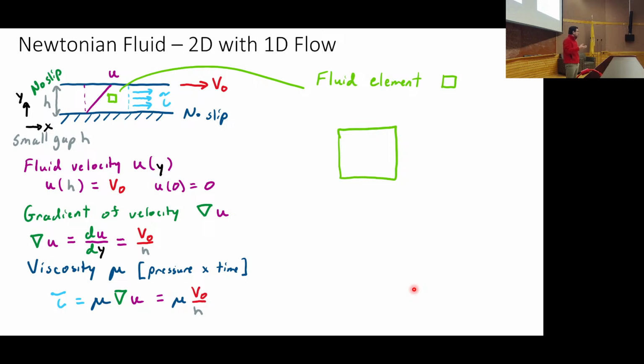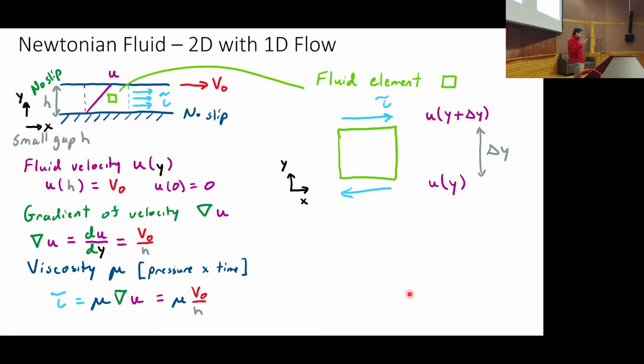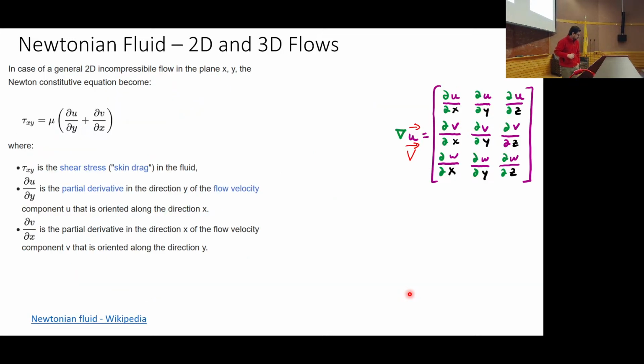And it's good to remind ourselves, as we showed a minute ago, that if you have a shear stress on one side, you have a corresponding shear stress on the other side, and this fluid element is still in equilibrium with the small element. So you're going to have these other arrows for shear stress. The fluid is being distorted. You've heard shear. You know shear. That's what we're dealing with.